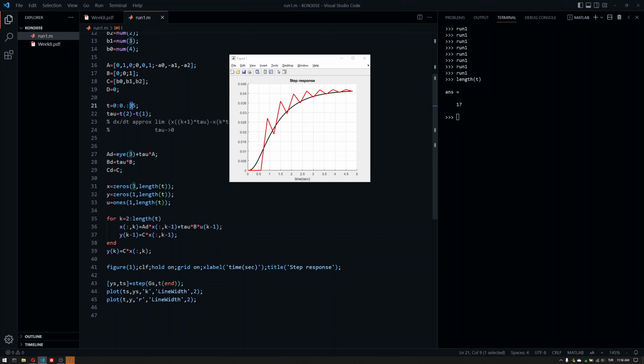And it seems like 0.1 for the time being is a good approximation here that we can use. Of course, this could be an approximation. There's a trade-off here. And if you're okay with the approximation, even though we have slight differences here, I might be okay with this. I might not push it to 0.01 to have the perfect value here, because most of the time we look for ISE values, ITSE values, so integral time squared errors, absolute errors, or whatever, to optimize stuff.